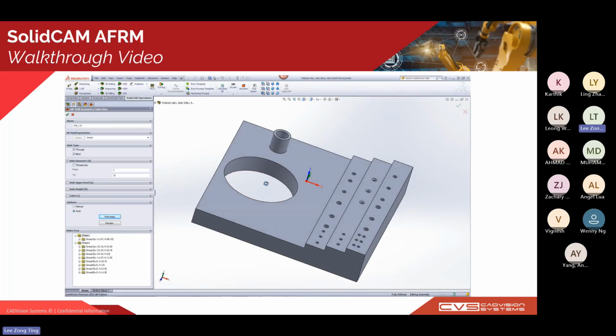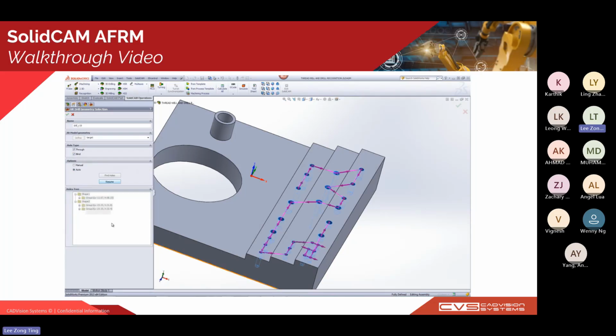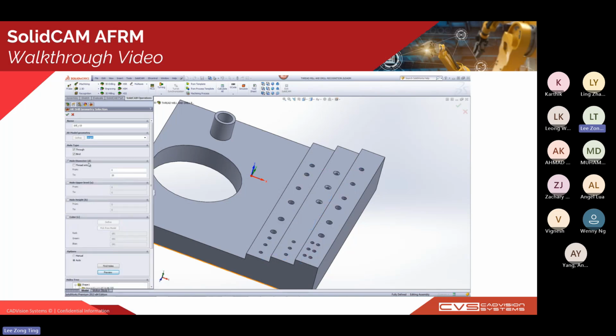So you can see on the left side, left bottom corner right here, there's a hole tree, and they group all these holes by their shapes, their diameter, their depth, and we can do different operations based on the groups we want. So for example, I want to remove the shape number 1 hole. So we just remove it from the operations. Okay, go ahead and preview it to find all the holes first, to see how all these holes are located in your 3D model.